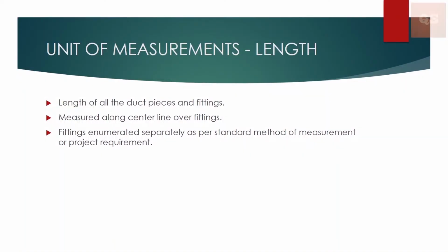In this video, I will be explaining how the length of duct measurements is done. Basically, all the duct pieces are measured in a linear way, and the fittings can be included or can be separately enumerated. It depends upon the standard method of measurement used in your project and the BOQ, what it specifies, what your project requirement is.